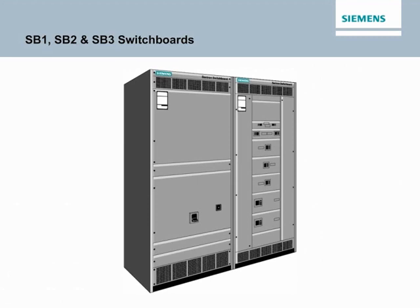The continuous rating and through bus can be sized on the basis of anticipated future load demand. Trip units or fuses of lower ratings can be installed to meet present load demands and change in the future as load increases. SB1, SB2, and SB3 switchboards are built to UL 891 and NEMA PB2 standards and provide the rugged construction and service flexibility necessary in systems for industrial plants, high-rise complexes, hospitals, and commercial buildings.